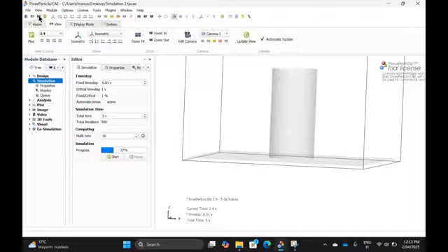So okay, let's drop a sphere on the bottom and stable. Everything good. Increase the time step a little. Unstable, catastrophic. So make a Newton's approximation and find the stable time step. So I decreased it, and 0.05 works like a charm. So particles are in there, they're moving a little, but that's it. If I increase the time step to a certain point, let's see what's happening.